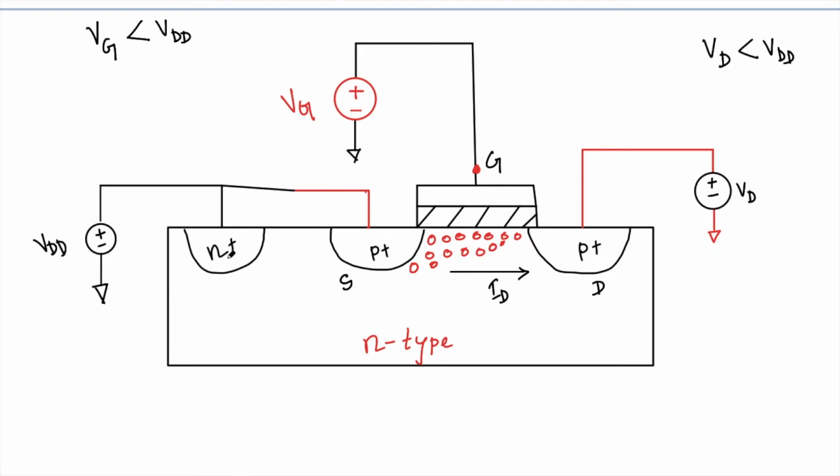Now the other thing is, for this PMOS, the bulk terminal B has to be connected always to the highest potential of a circuit. Just like in the case of the NMOS, it was connected to the lowest potential, to avoid the PN junctions being in forward bias condition. So if I connect this one at the highest potential, then whatever this N and this P, it will always be in a reverse bias condition. Okay, so this is the condition that we need to follow.